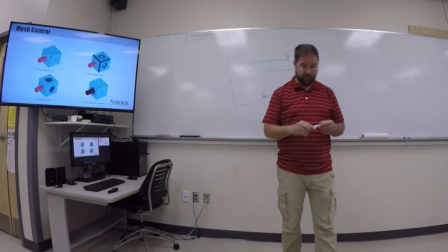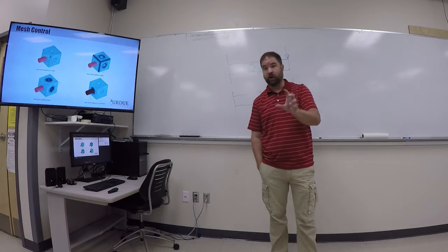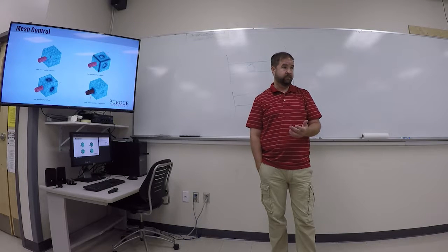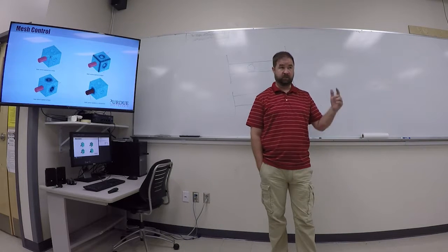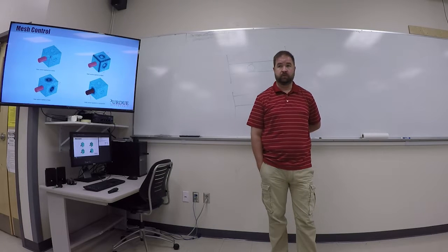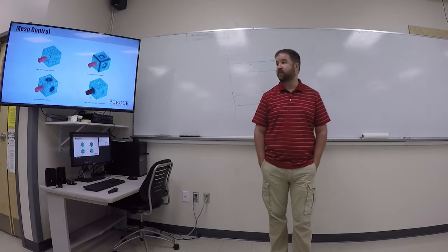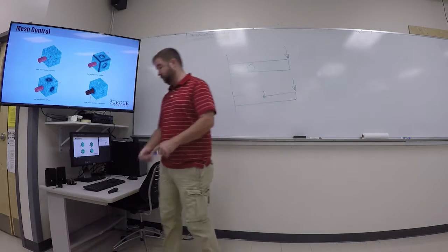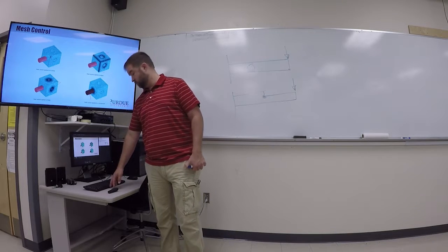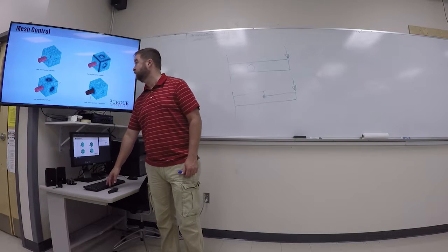So what typically the process is, is that you do an analysis, you look and you see where the stress is high, and then you reduce the mesh size in that area, and then go and solve it again. Okay, so it's kind of an iterative process as you work towards the final results you get for the problem. Okay, so you have that ability to control that. You'll have to start doing that in assignments 6 and 7 to improve your results. Some of you guys haven't done some of the other assignments, you can use them in those places too if you want to.